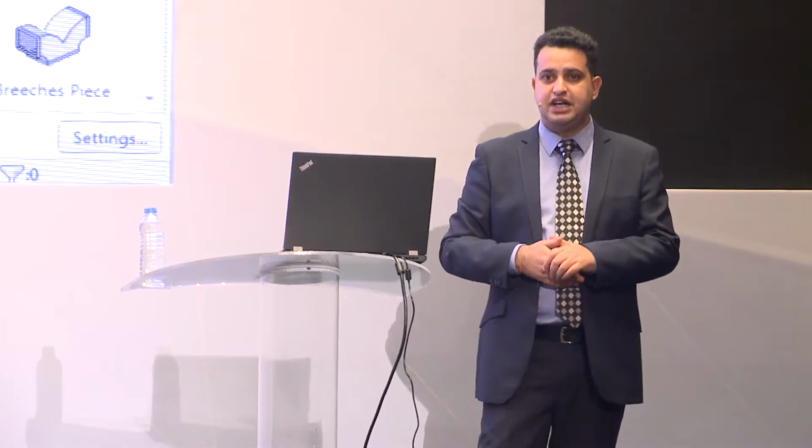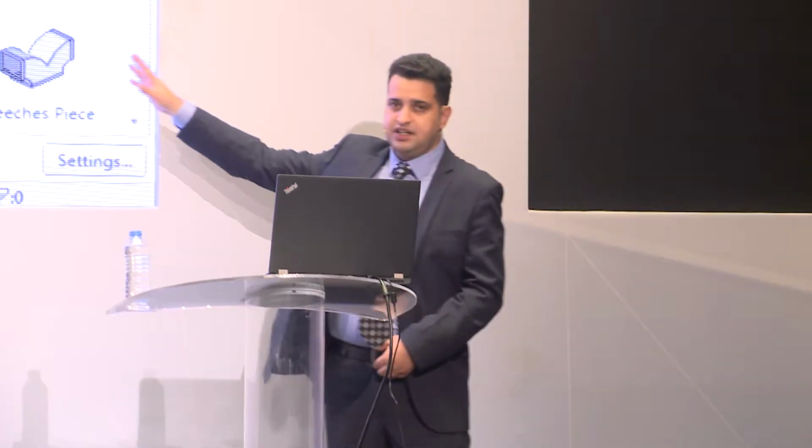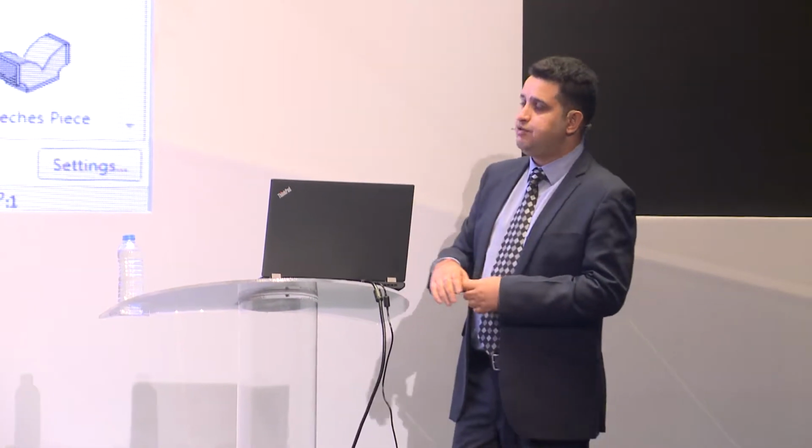Now, this is if I need to model from scratch inside Revit. On the right-hand side, you see the content here. The content is coming from the fabrication solutions, and we'll be using the same content in other solutions as well later on. This content is LOD 400. This is fabrication-ready content. By default, it is DW144 as well as SMACNA specifications, which are already built in. Now, this is how I'm going to do it here.